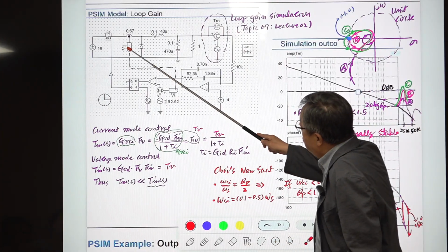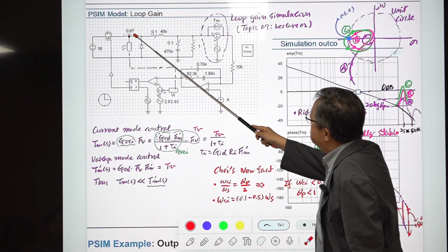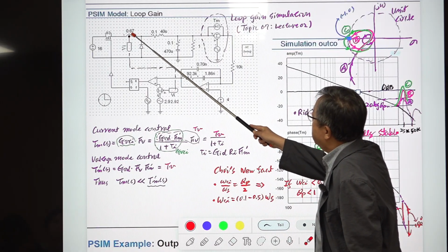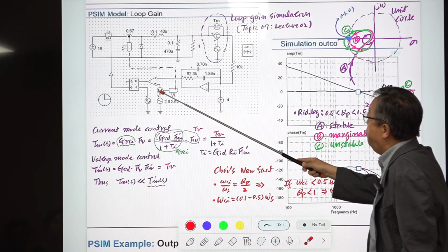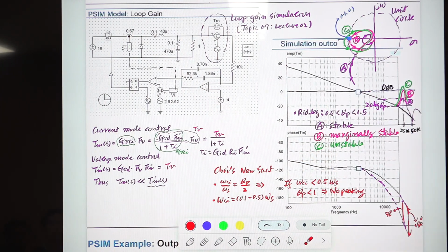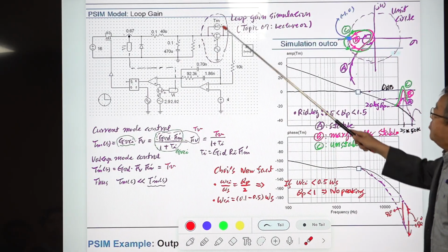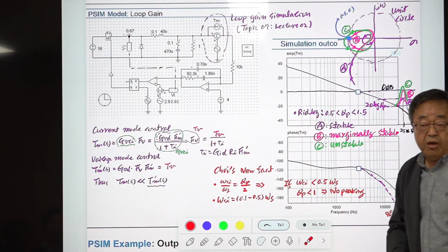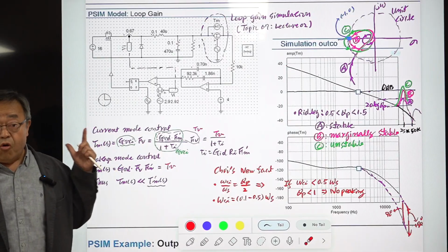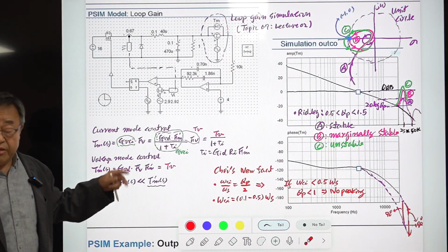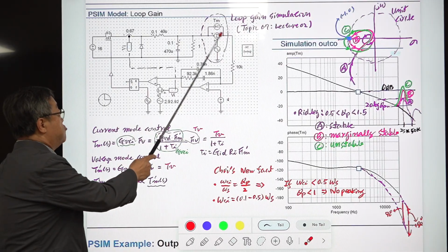First, there is a connection inside of this model. The switch current is sensed with this current sensing network gain and fed to this input port of the PWM modulator, and this is our voltage compensation. And this is something you need to use to measure the loop gain of this converter, or to simulate. To measure experimentally you need something very similar to this.